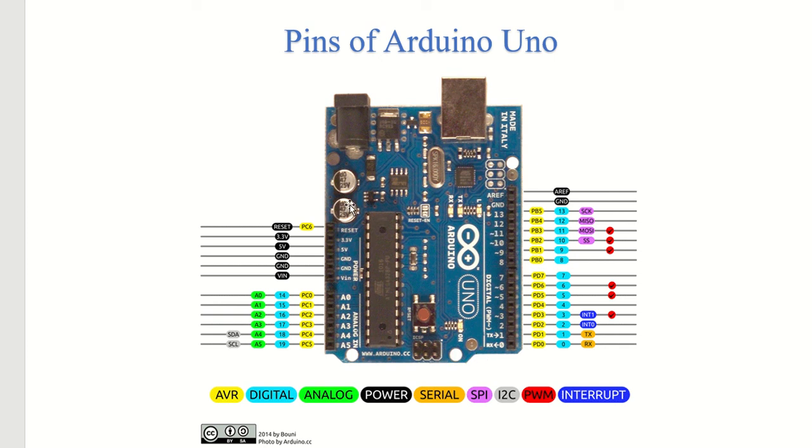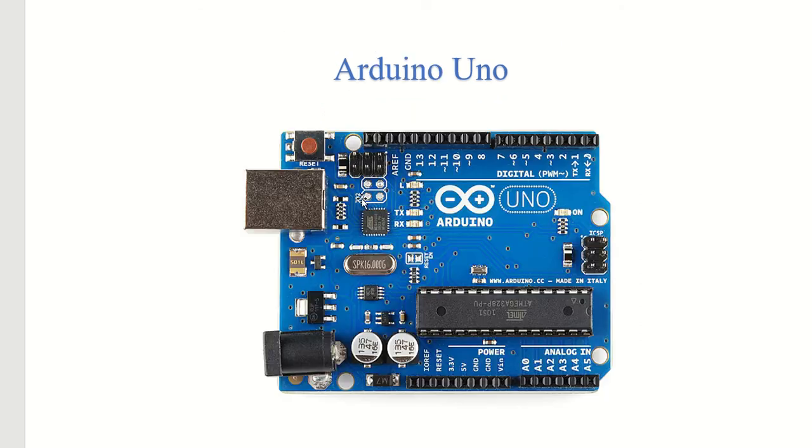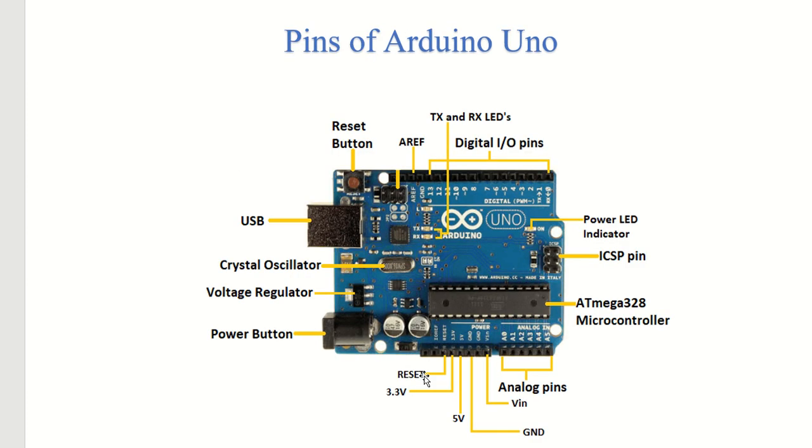Okay, they do use it, but they've placed it somewhere else, probably here, right? So probably not present in this Arduino, but in this Arduino we have IO ref, which is the input output reference pin. Right here you can see around my cursor. That pin provides the logical reference voltage for shields that use it, and it is connected to the 5 volt bus. Here also you can see input output reference.